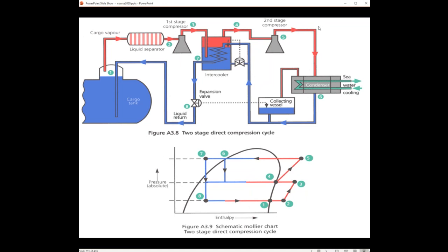Okay, what has been added on this drawing is only two elements, namely a drum, which we call the intercooler, and this second and maybe a third compression. I explained why we added this second and this third compression: to keep the efficiency high enough and not to go over this rate of 1 to 6.